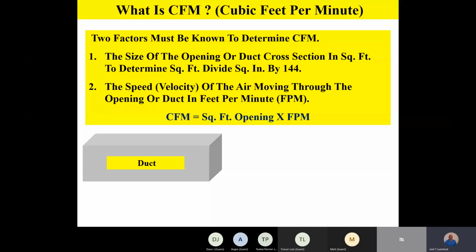Okay, and so when we look at friction loss, we have to remember this is per each 100 feet of that duct. So the air duct calculator gives us, we can design a duct around a particular size duct at any given velocity or CFM, and it'll tell you our duct size. It'll also tell us the amount of friction loss per 100 feet of that selected duct.